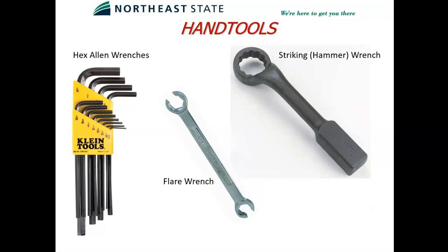It's got that opening on it to allow you to slip it over your brake line, so the metal line will actually go in that slot. Then you can slide the tool down along the brake line to the flare nut, and then it looks like 1, 2, 3, 4 sides contacting that nut,